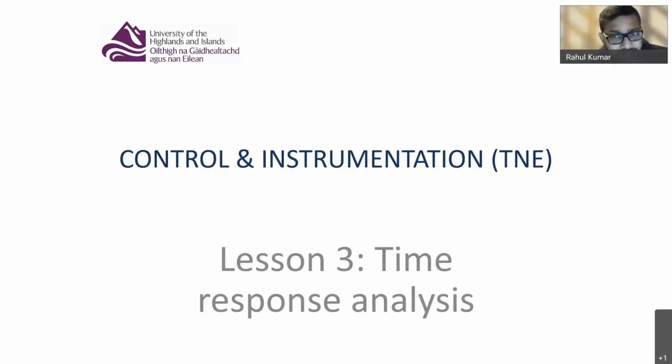Now, I also mentioned that the first step for developing your transfer function is to convert the time domain equation into complex frequency domain or S domain, right? One of the advantages of doing that is it simplifies the equation, because in time domain, if you have any derivatives, they are very difficult to implement in MATLAB.